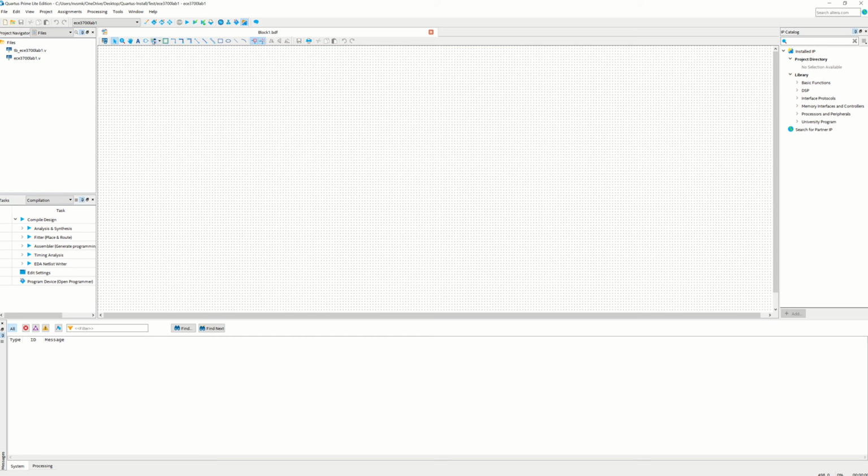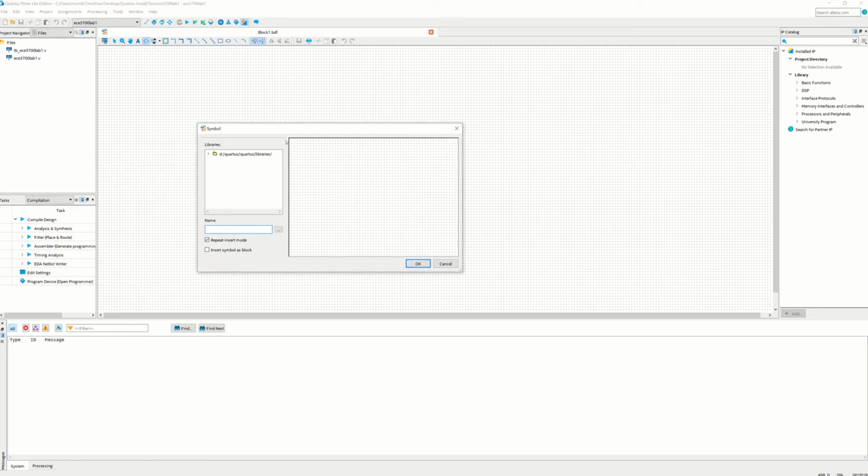If you see the AND gate symbol, this is basically the symbol tool. If you press that, it should give you a drop down menu, something like this. That should have all the symbol libraries for your gates. Once you click on that, you want to go to primitives, and inside logic here, you should find all your gates.